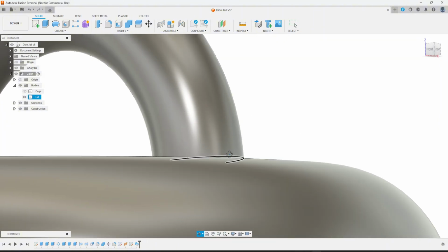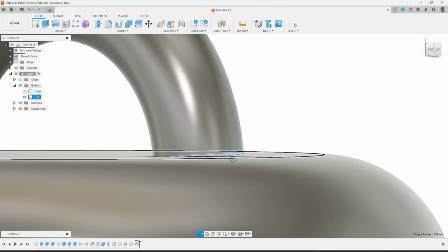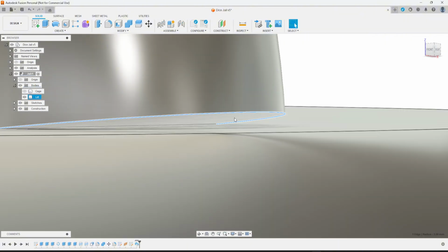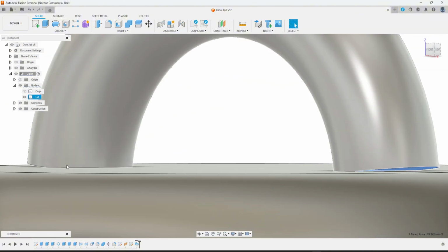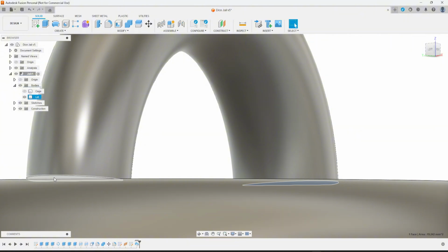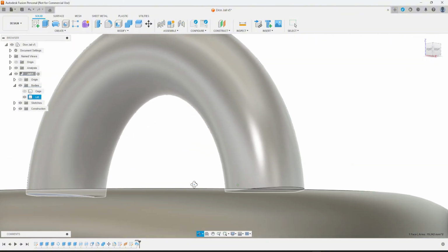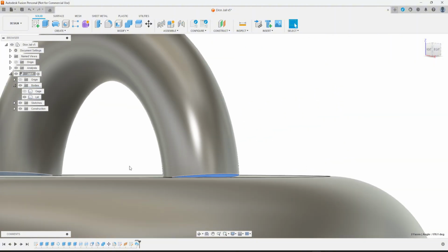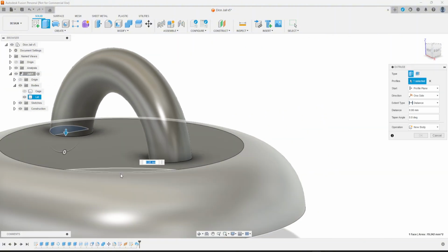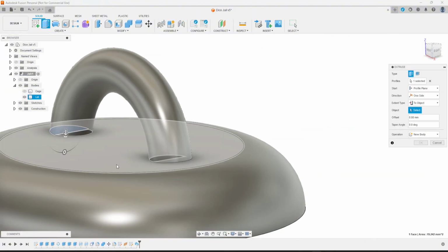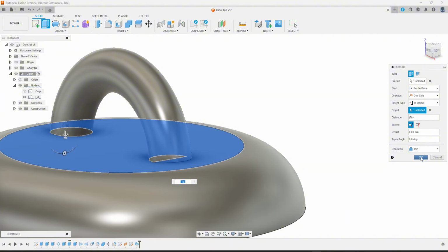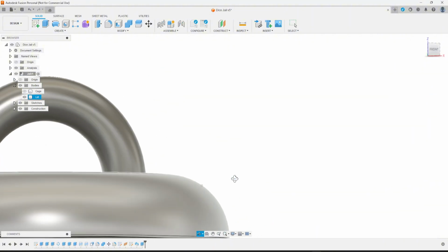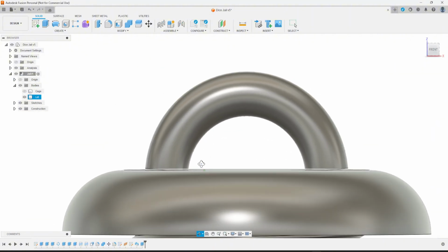And then to fix that angle problem, you can do it a bunch of ways. I just did it quick and dirty. The way you can do that is just highlight each of your faces. I had to do this twice for some reason, but it'll work out. Highlight each of your faces. And then extrude, to object, and select the top of your top lid. And then it'll create an extension from each face.